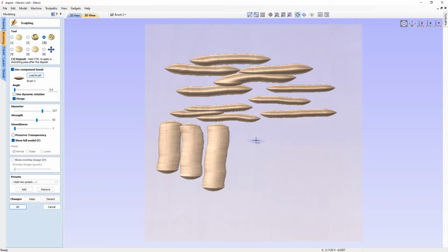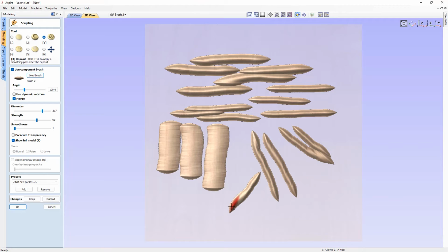So if you press the R key on your keyboard, and then using the scroller of your mouse, moving away from you actually rotates this clockwise like so, and then we can let go and we can go in this motion. Scrolling towards you just makes that in an anti-clockwise motion, and again we can do that as well, and again we can do that over here, so like so.